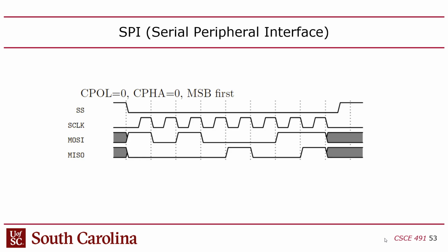So that's how this generally works. In this case, CPOL and CPHA are 0. The way I can tell, maybe this is a dumb approach, but the dead giveaway for CPHA is all you have to do is look at the beginning of the exchange. If the data starts changing, like you see here, it's a don't care.